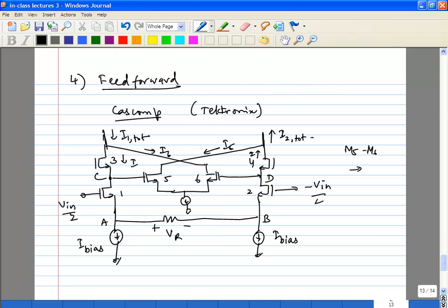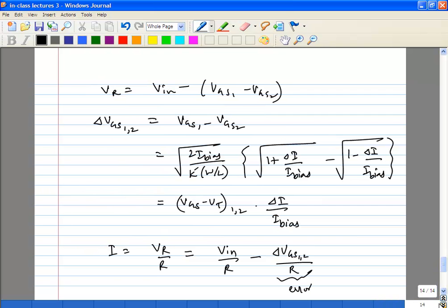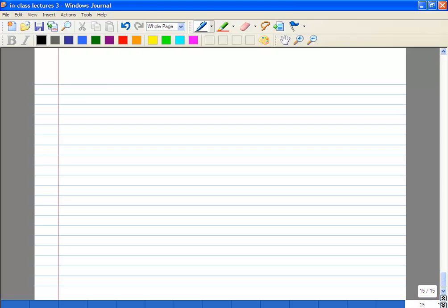We also know the voltage gain from, let's say, the positive input to C is approximately -1, and same thing on this side. So you know the voltages at C and D approximately. So let's write that also. So this is Vc and Vd.